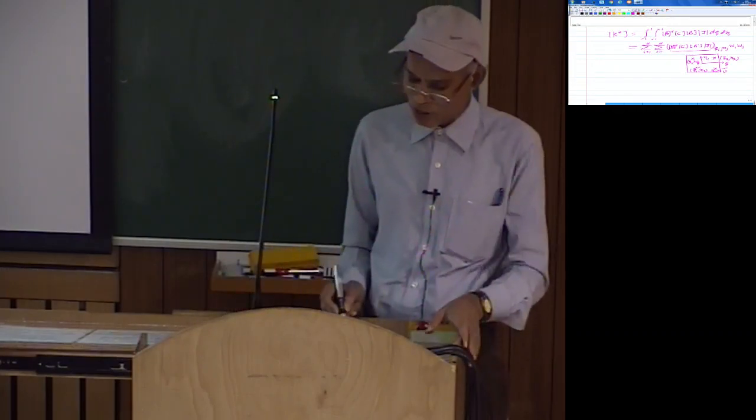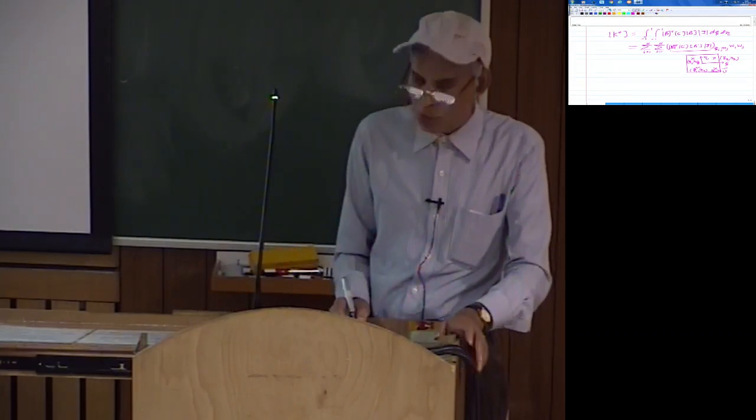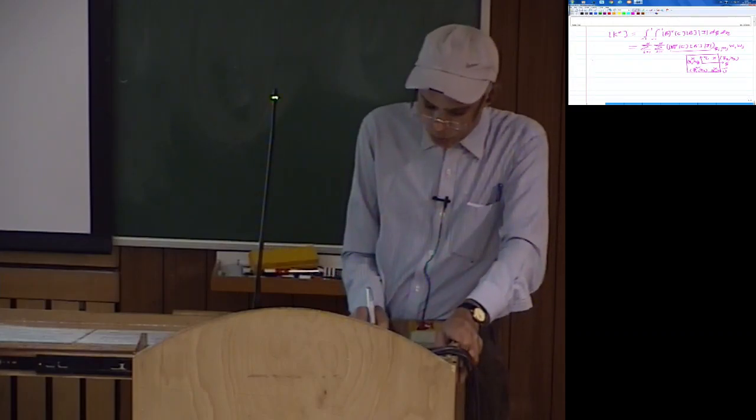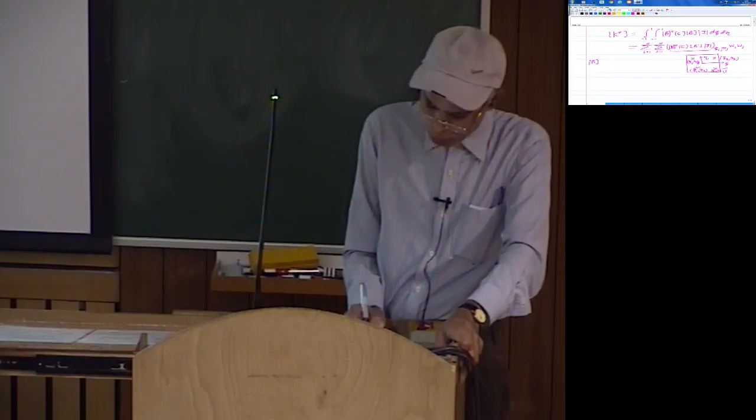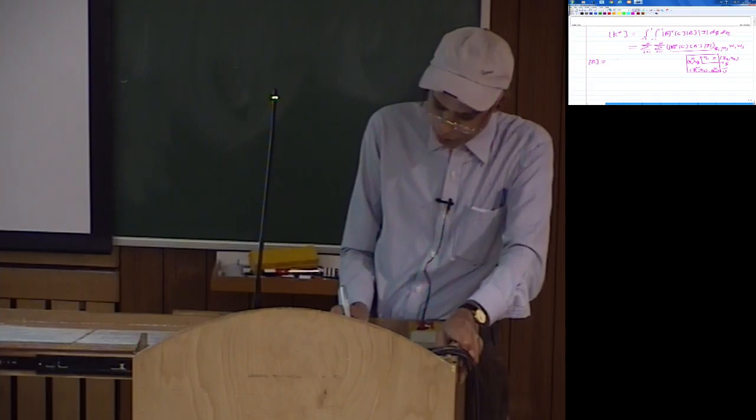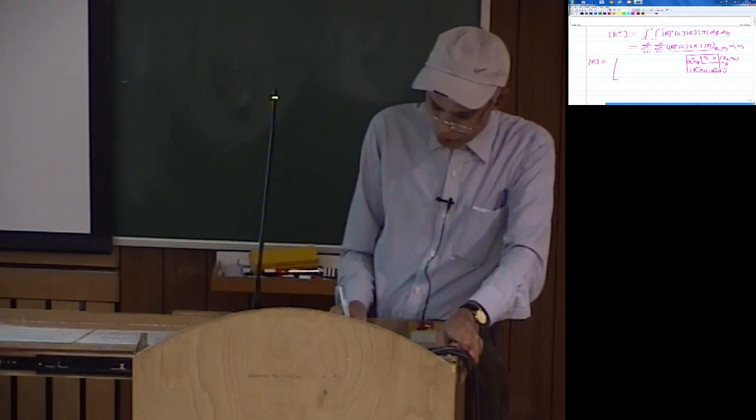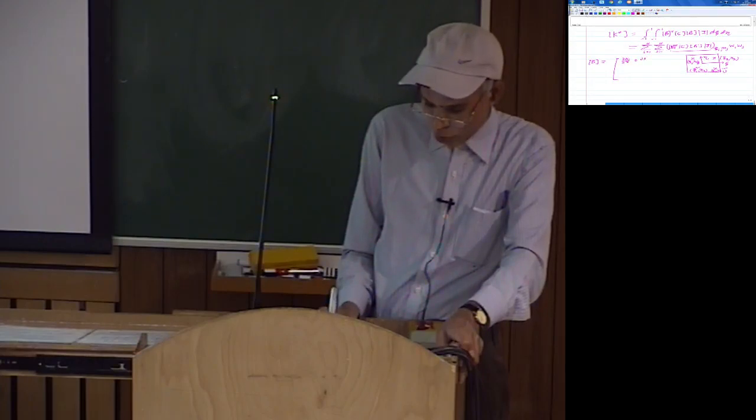What it actually means is that for defining B, you need to, depending on the problem, suppose it was a plane stress or plane strain problem, then your B matrix is like del N1 by del x, 0, del N2 by del x, and of that nature.